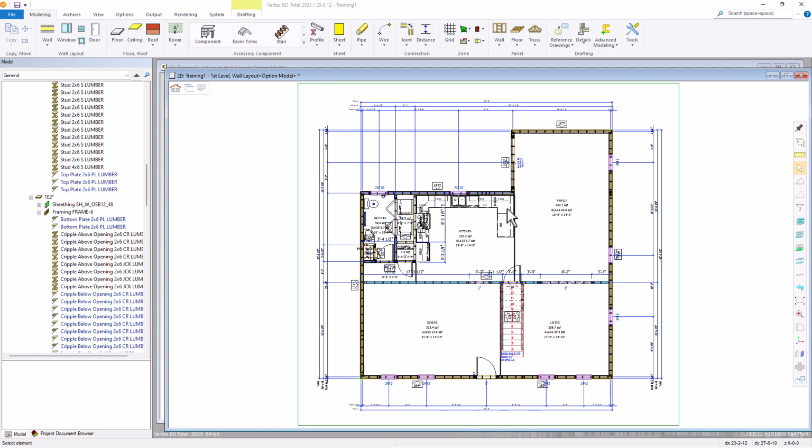Replacing the panel drawings will delete the existing panel drawings and prompt the user to select a new wall panel template. Updating the panel drawing will keep the existing drawings, but update the material schedules and the existing drawing and elevations on the panel drawing.